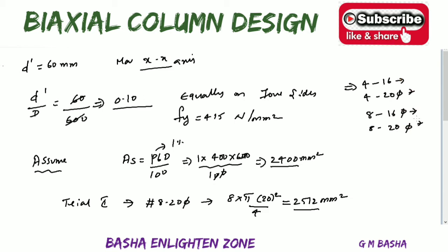Whatever value you get more than required, you have to choose that particular dia. Why am I choosing 4 and 8? Here we are choosing the option of reinforcement equally on all 4 sides, so 4 will be suited and 8 also. I am not taking 6, because 6 means it will be equally on only opposite sides.